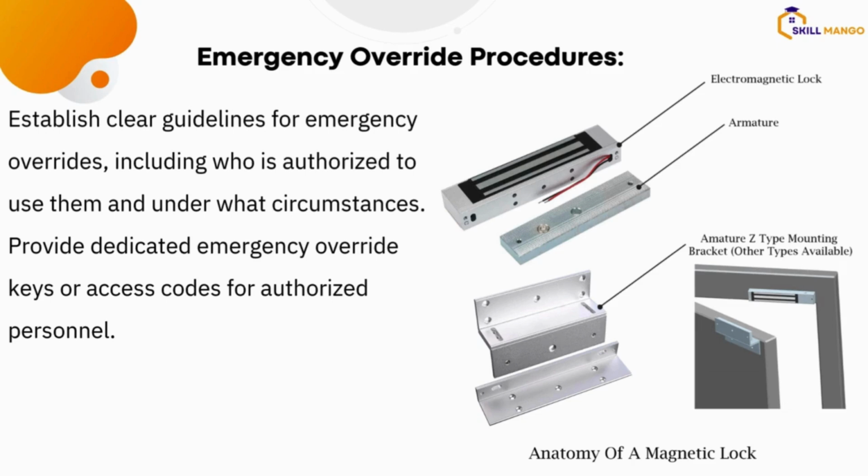This is very important. Then also, you have to look at the ZL bracket. When you are buying your maglock, you have to ensure that you buy your ZL bracket. The ZL bracket is the bracket you're going to be using to mount it on the door and on the frame. Looking at this picture, this is the connection. The maglock itself is on the frame and the armature is on the door. The ZL bracket is carrying both components and ensuring they're well aligned to contact each other,